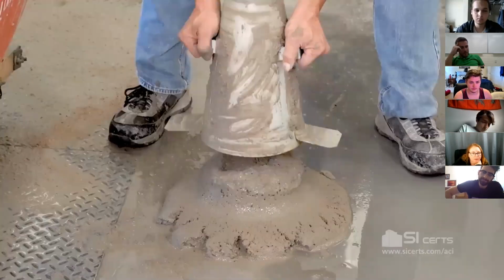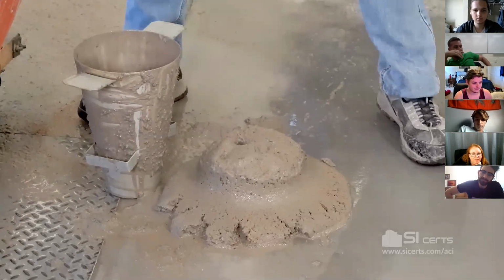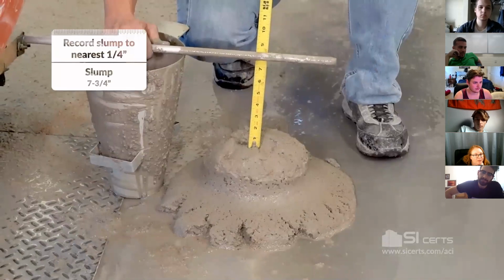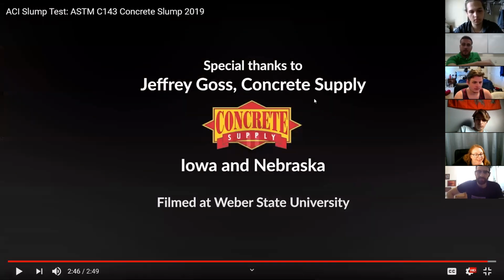Ooh, it's messed up. This is slump. This is a high slump. Invert the cone, measure down to the offset center, and get your reading for your slump. Too much water. This is slump.